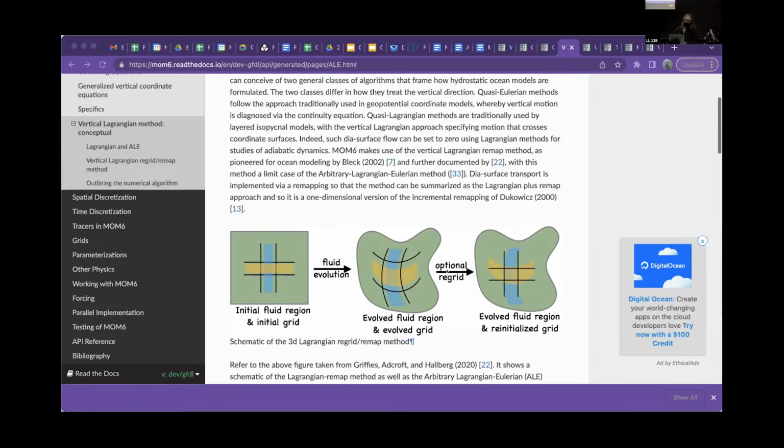Now, there is a need, and I think if you did any Lagrangian mechanics, you probably remember that at some point, these fluid elements will get so contorted, they'll rip apart and you lose all continuity of your ability to maintain smoothness of the properties on your grid. So you have to do a regrid step. And when you regrid, you have to then map your fluid properties onto the new, regridded grid. So there's a regrid remap step.